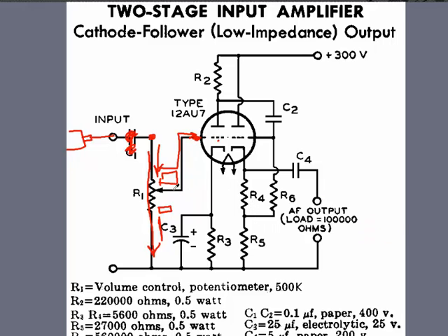So I think you've just learned that, as this potentiometer here, if you'll notice, it's a 500K. Well, if you turn that thing so that you had 490K down on this end and only 10K of resistance on this side of it, that a whole lot more of the current would flow that way, ultimately putting a higher voltage potential here at this point, and not much would be making it down through this way. Hope that makes sense to you. It's just a basic voltage divider principle here, applying less voltage here or more voltage across this point here is what we're ultimately trying to do, and varying the volume into this amplifier.